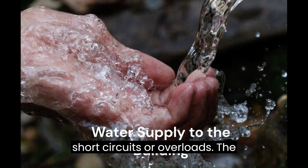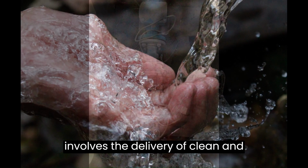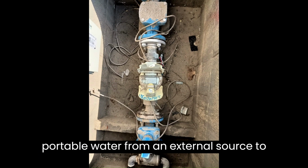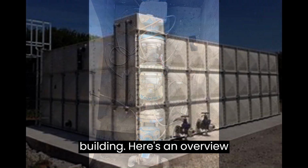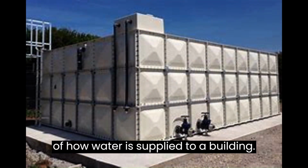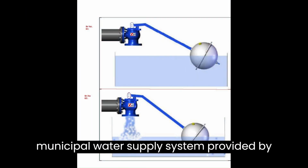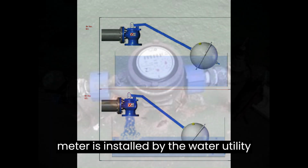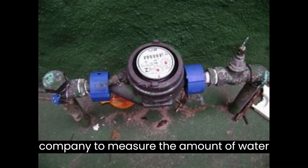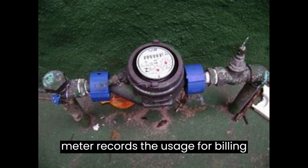The water supply system for a building involves the delivery of clean and potable water from an external source to the various points of use within the building. Here's an overview of how water is supplied to a building. Buildings are typically connected to a municipal water supply system provided by local authorities. A water meter is installed by the water utility company to measure the amount of water consumed by the building. This meter records the usage for billing purposes.